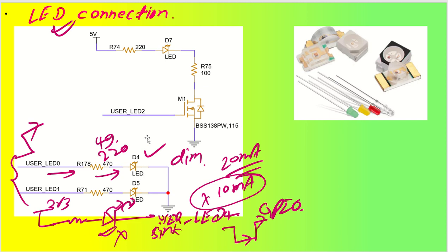One very powerful technique of connecting your LED is through a MOSFET, where there is a need of very high current to drive the LED, so that you can have, let's say, flash LEDs or something like that, or maybe RGB LEDs. In that case, you cannot source or sink that current through the microcontroller pin.